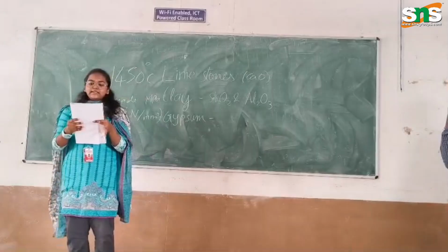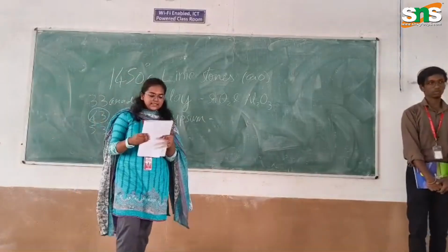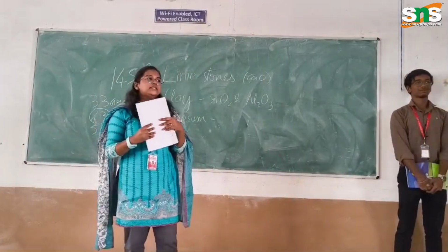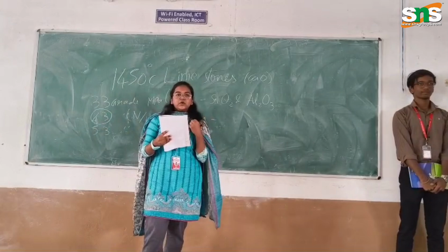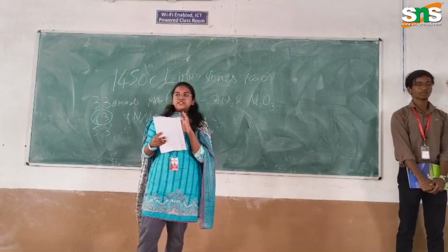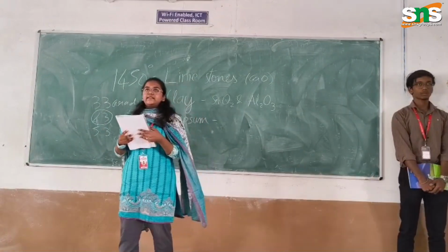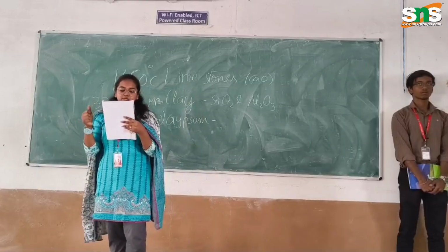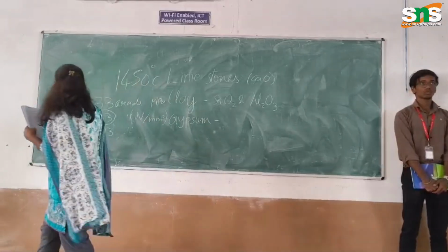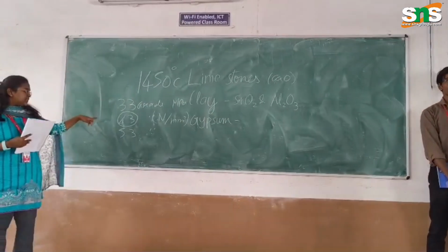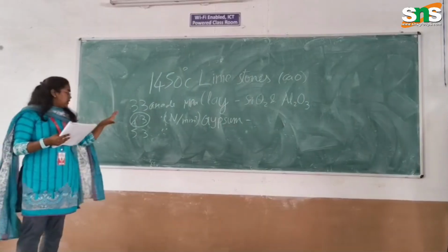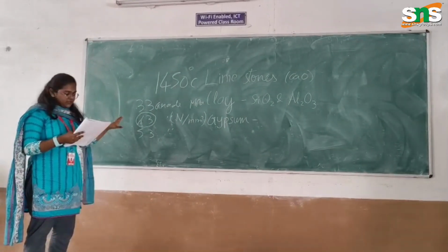Two main strengths, that is compressive strength and tensile strength. Compressive strength is how much load, weight or pressure a cement can withstand when it is pressed or squeezed. Cement grades like 43, 33 and 53 are classified based on compressive strength.